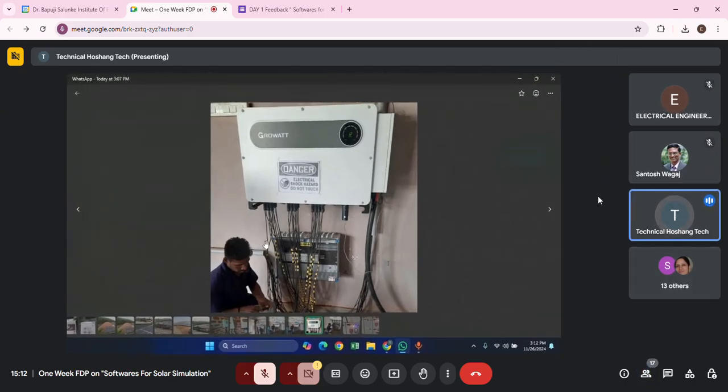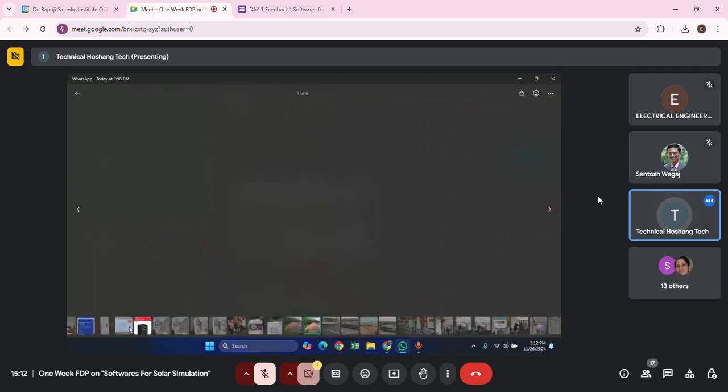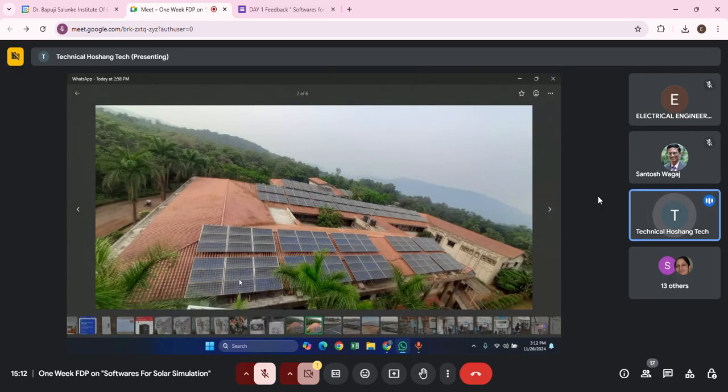This is the DC side where, from this image, the total 9 panels and 9 panels are connected together in series. All these panels are interconnected in a series format. In this way, you have a positive terminal on this side and a negative terminal on this side. This together stacks up. You see a small wire here, right? This is a heavy wire, so this contributes to a single table.